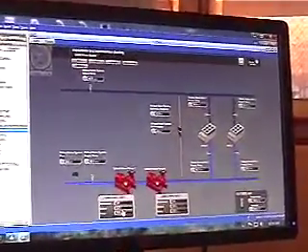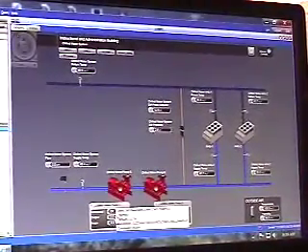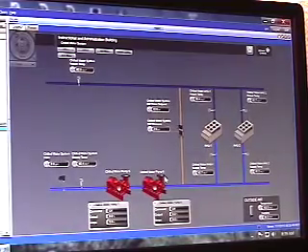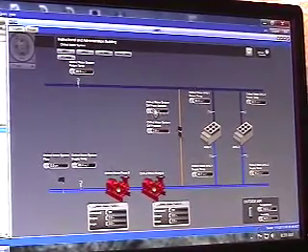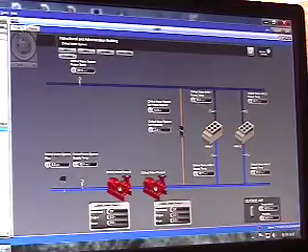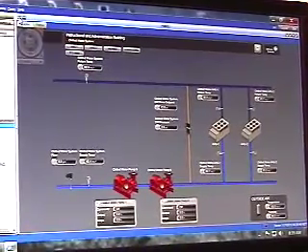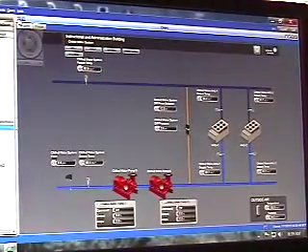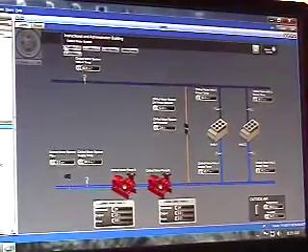We've determined what the minimum current draw is when that fan runs. It's a nice way of doing it, because if a coupling breaks or something like that, it's just free will, and you're not going to get status because you're not pulling enough amps. A lot of times on a switch, if it's not adjusted quite right, you'll still show a status. So when this turns on, you will get a status, it will have a spinning wheel, but you're going to get a current draw through it as well. When the system's enabled, the pumps turn on, and we just control to maintain a differential pressure. Those pumps are in parallel, not series, right? Yes.